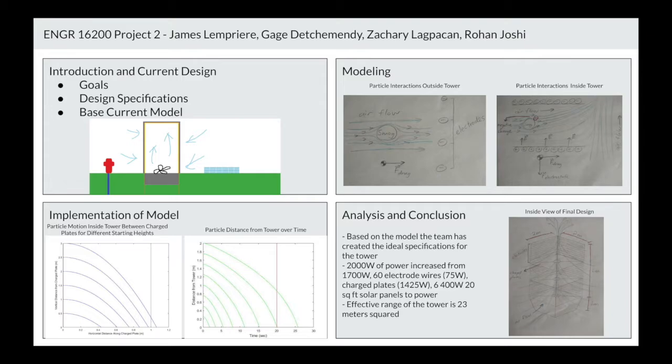When the equations were plugged into the MATLAB model, some interesting issues were first discovered. The option for a pre-filter would not be feasible, as the fans used were too large, as they did not move enough air to cause the air to move at a velocity greater than the expected reduction in airspeed through the filter. Thus, this element was eliminated from our model. Once this correction was made, the model runs accurately and depicts the effects that an electrostatic precipitation-based smog reduction facility would have on the pollution particulate in the air surrounding it.